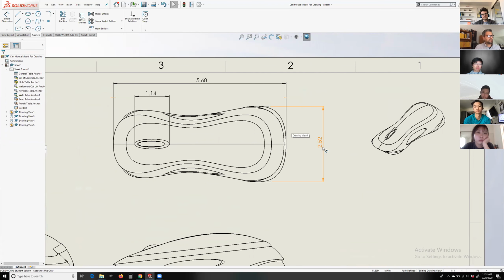So if you do want to get rid of some of those items, you can, to clear out some space for your other stuff there. Just go into edit sheet format and start deleting some of those, and just be careful with it. Maybe I'll link to something that gets into editing these title blocks in more detail, because you can really just create your own title block, something more unique to you and to the information that you want to show.